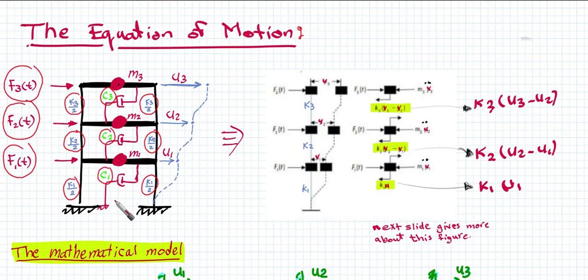So based on that, under these motions, we're going to find that the floors are going to be displaced U1, U2, and U3 horizontally under these loads. This means that we are going to have horizontal movement at each floor level. Then we are going to make the idealization here, which is going to be, as we said, a cantilever column.